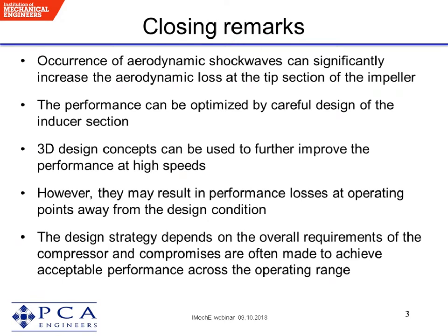So what we found is the overall parameters of the diffuser, such as area ratio, throat area, the incidence on the blade, or average incidence of the blade, was more significant than the 3D design.